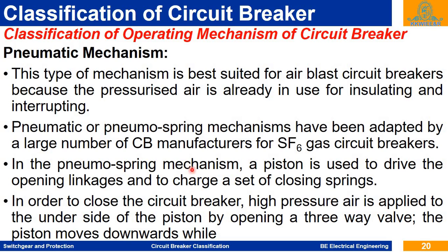This pneumospring mechanism has a piston used to drive the opening linkages and charge a set of closing springs. So the pneumatic cylinder and piston are used with control valves to open the linkages and to charge the closing spring, to store the energy in this closing spring.